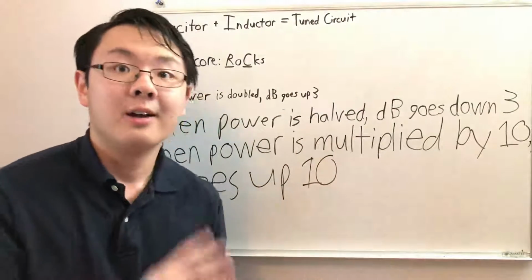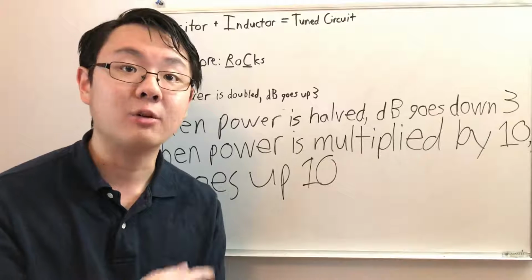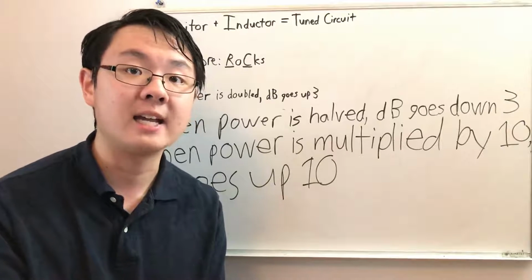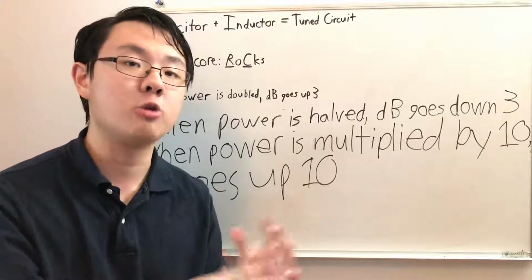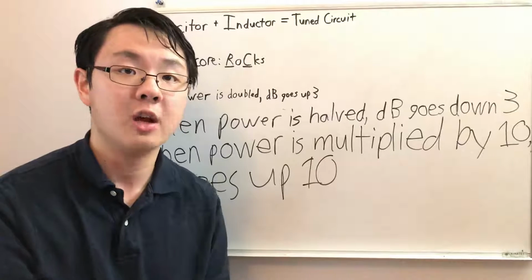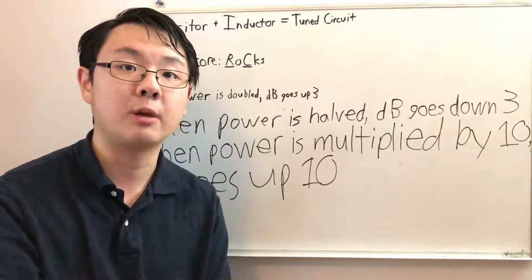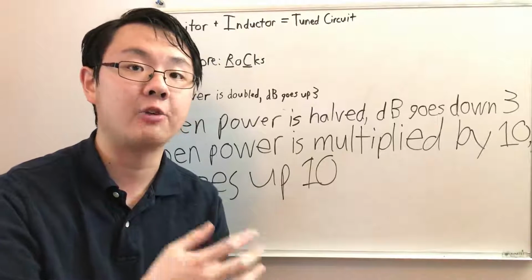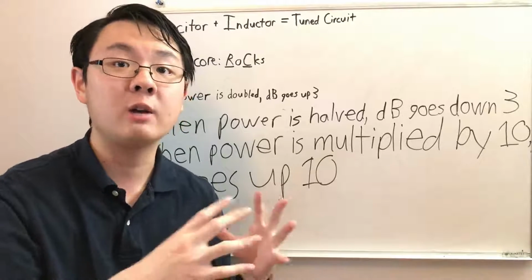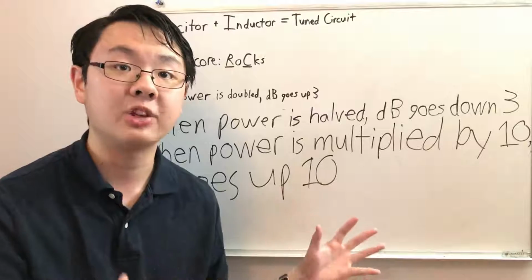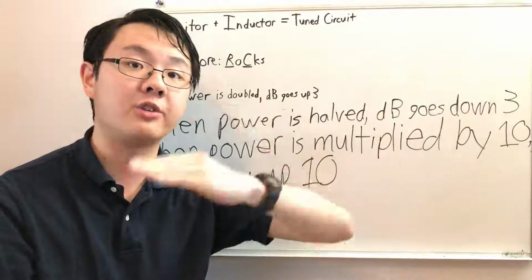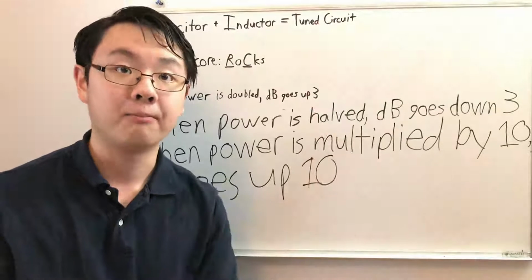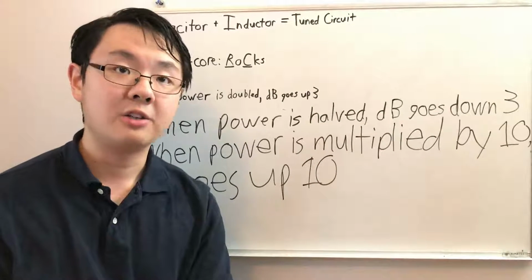Is it magic? No, what you probably have is a large capacitor in your circuit. The capacitor starts up with no charge in it, right? So you see no resistance. But as the capacitor charges up from the power from your ohm meter and gathers energy, it increases the resistance in the circuit. This explains the phenomenon of the ohm meter reading just gradually increasing over time. All right, that's the last thing you need to know on this section.